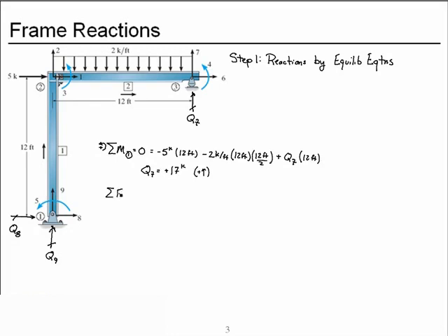And I solve forces in the x direction. I'll choose to the right as positive. I get a contribution from the reaction at degree of freedom 8. I have the applied lateral load of 5 kips. I solve that and find the reaction at degree of freedom 8 is a negative 5 kips, where to the right would have been positive.